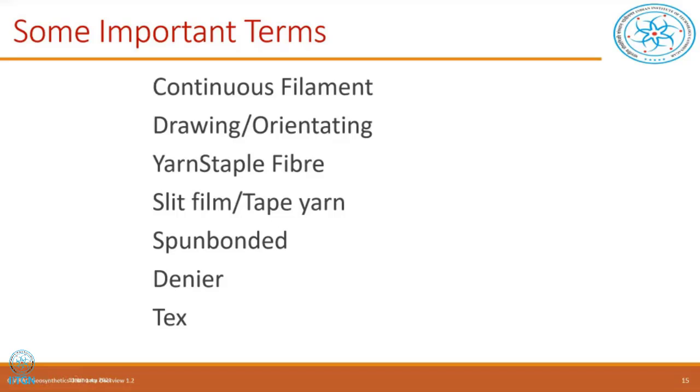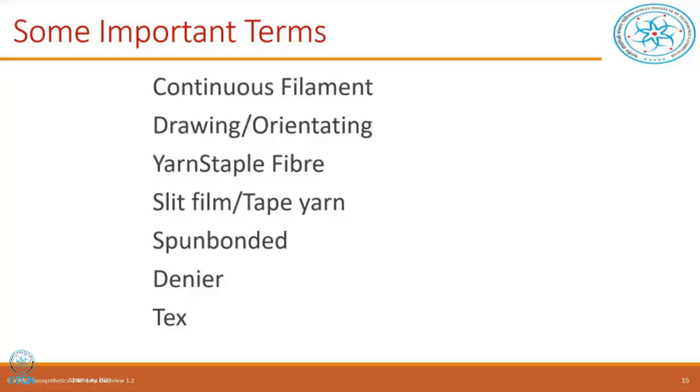When we come to the cloth, that means geotextile, I will show you both things also. Then another word which you use is spun bonding. Spun bonding is a process by which, from the filament to the sheet geotextile, one single go is called spun bonding. Obviously, spun bonding is a comparison between a product which is made from a sheet film kind of thing or from staple fiber kind of thing.